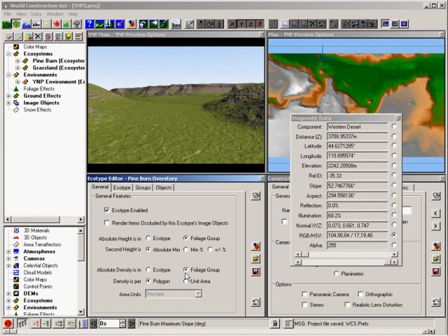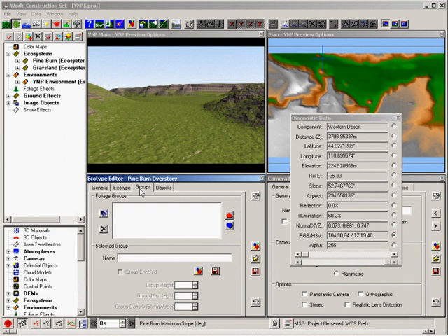By default, density is per polygon. This minimizes render time as fewer polygons are rendered as distance from the camera increases. The downside is that the density of trees will vary with changes in fractal depth and distance. Not good if you're using low fractal depth preview renders to evaluate a high fractal depth forest. To make density independent of fractal depth and distance, change density to per unit area and leave the area units at hectare.